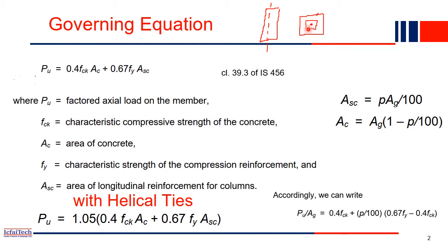It is an axially loaded column. So how did we get the 5% value? This length is basically 0.05b, and this one is 0.05d, right? So total 5% area. This 5% came from the concept of a short column.